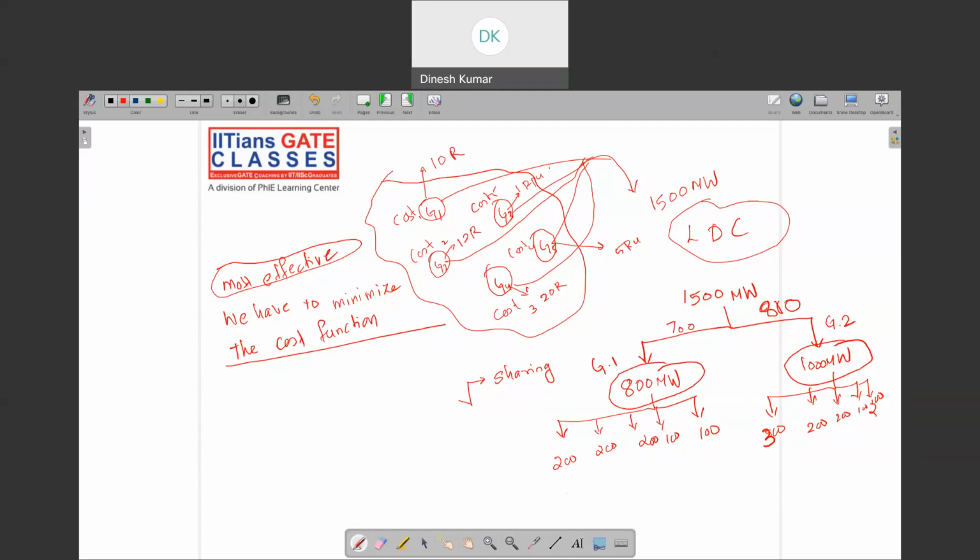But the problem is that if you look at the performance curve of most electrical machines, you can just go and check the synchronous machine performance curve. The efficiency is maximum at some load which is not the rated load, right? It is less than the rated load. We will get the maximum efficiency at this particular point.